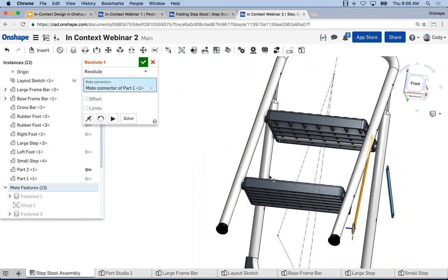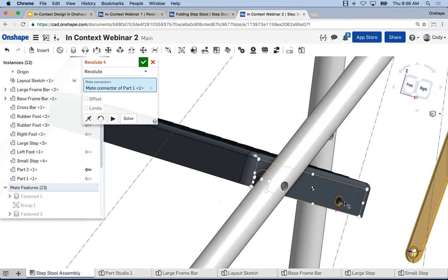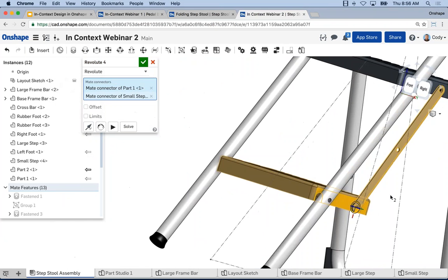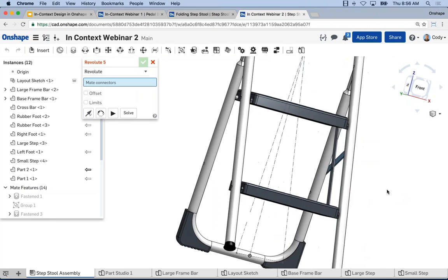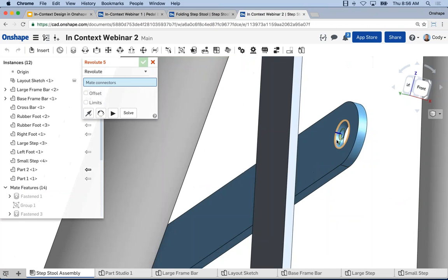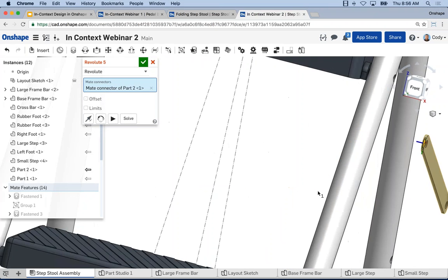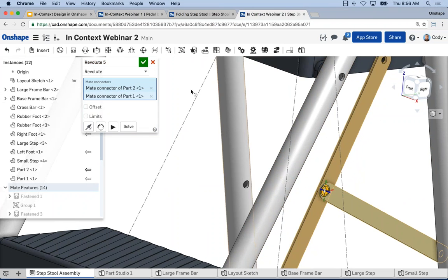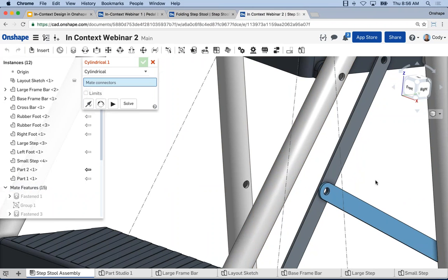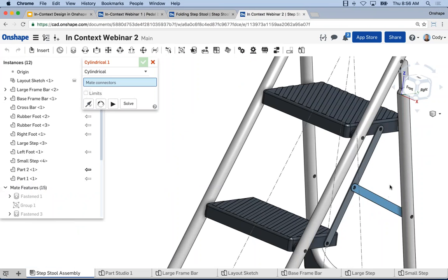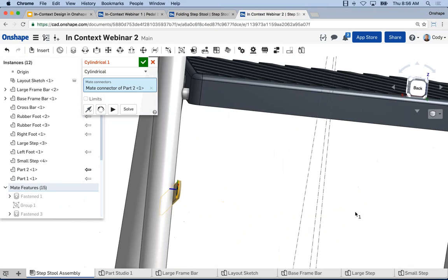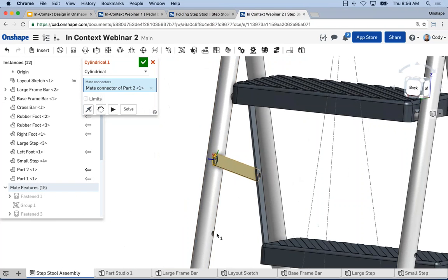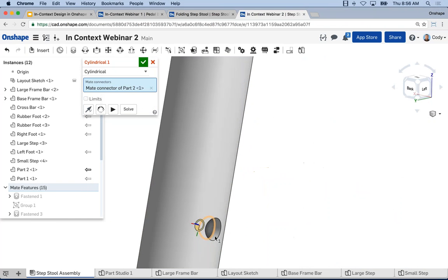It's free to move just like any other part, which means it needs to be mated with the correct degrees of freedom. All right, so I can go through, add a few revolute mates for all the rotation that this thing needs, right? And get my kind of realistic assembly motion that I'm going for here. So now we've got, let's add this last mate.